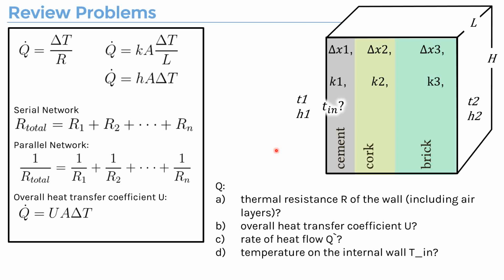But in this course, we try to have more significant heat transfer. So if the resistance is really low, that makes the overall heat transfer coefficient really high. So we can read very directly that a very high value of overall heat transfer coefficient will tell us it's a very good design in terms of heat exchange. So that's practice on getting the overall heat transfer coefficient. You also need to calculate this in your condenser design.